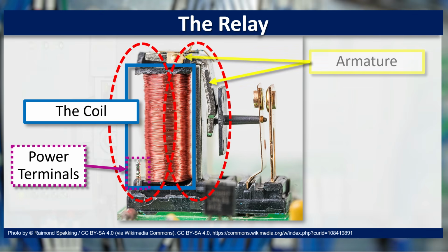That magnetic field is immediately put to work pulling on the metal swing arm bar, called the armature. The field pulls the top down, and the linkage portion is pushed outward towards a fixed contact reed until it makes contact, closing a potential circuit.